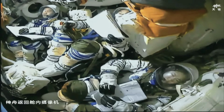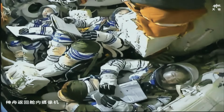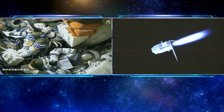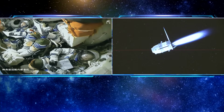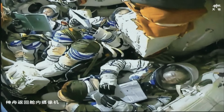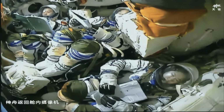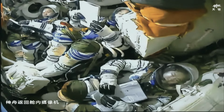Yes, exactly. From the previous video, we can see that although it is a 3D animation, it represents the real-time status of the spaceship. At this moment, we are conducting the de-orbit burn, which means that we decelerate, shedding a remarkable amount of energy, so that the trajectory of the Shenzhou spaceship turns from a circum-Earth orbit to a trajectory which can dive into the atmosphere. With this very important measure, we can return to the Earth with the help of the aerodynamic forces, which reduce the speed of the Shenzhou spaceship, and then we can conduct the deployment of the parachute, and then we will be back on the Earth.